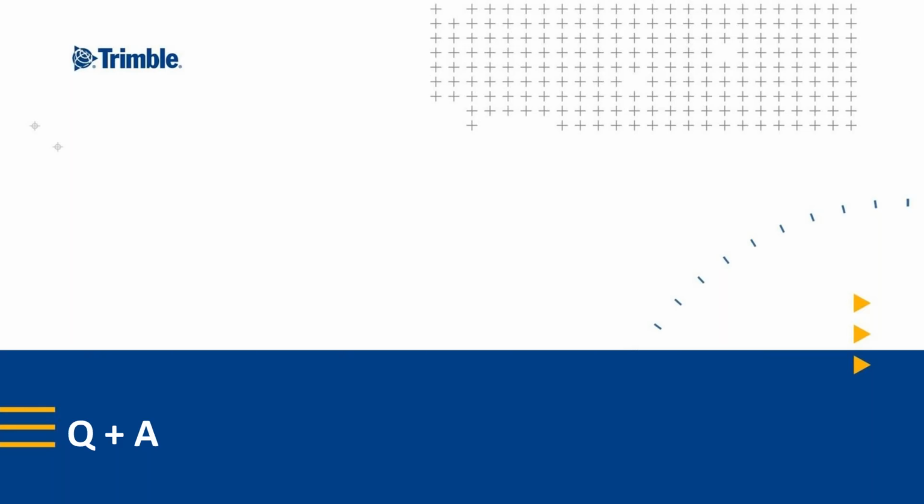Stephen is asking, Fernando, when you're measuring an opening, is it possible to measure the symbol key points, like those red dots, from different setup locations, or is it necessary to measure from one setup location? For the openings, you need to measure with the current measure mask. Once you leave the current measure mask, the data is lost. So for one opening, one door, one window, you need to do it from the same station point.